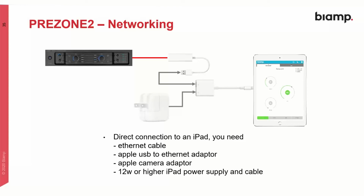Lastly, a lot of people want to control this device from a simple touch panel or smartphone, or in this case, a tablet. So with an iPad, you can actually have a direct connection. You do need a bit of external electronics in the Apple way. So you need an Ethernet cable, obviously, and that goes into a USB to Ethernet adapter. That then goes into the Apple camera adapter. And because the camera adapter needs to be powered, you need a 12-watt or higher iPad power supply and cable. So the power supply not only powers the camera adapter, but also supplies power to the iPad. So that's another option for a fixed installation where you want to have a touch panel installed.